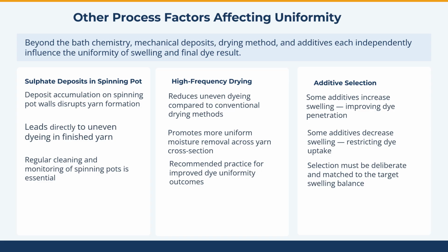Additives must also be selected carefully. Some additives increase swelling and promote dye penetration, while others reduce swelling and restrict dye uptake. The correct additive choice depends on the desired swelling balance and product requirements.